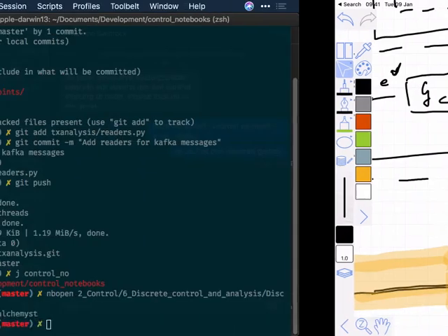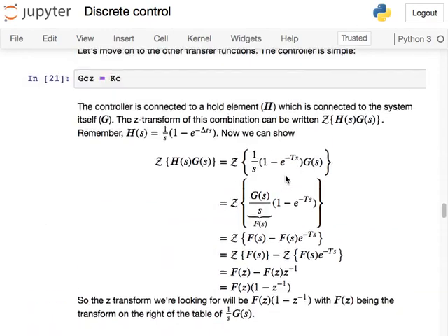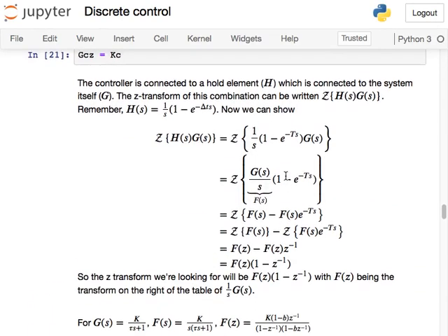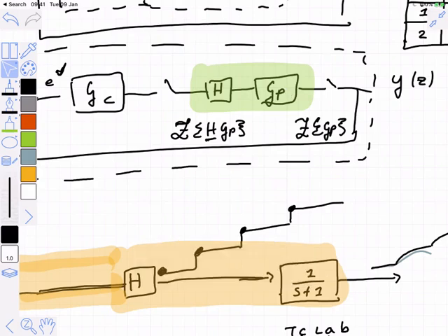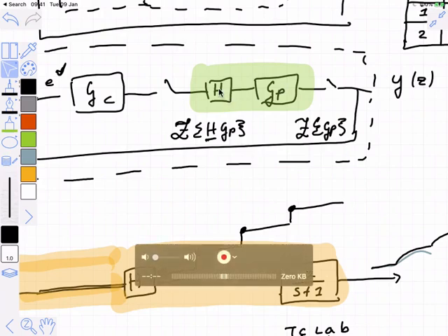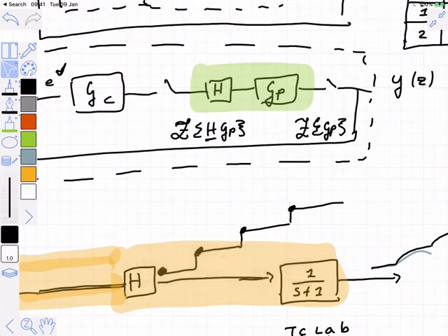So we've done this, and this is the calculation that we've just completed over here. This is why I'm doing this calculation: I want to know, if the controller does things at particular moments in time, what will we measure at particular moments in time after holding those measurements for that amount of time and putting it into GP. And I want you to remind yourself that that's very different from what I would observe if the hold element weren't there. So the math works out differently if the hold element isn't there.